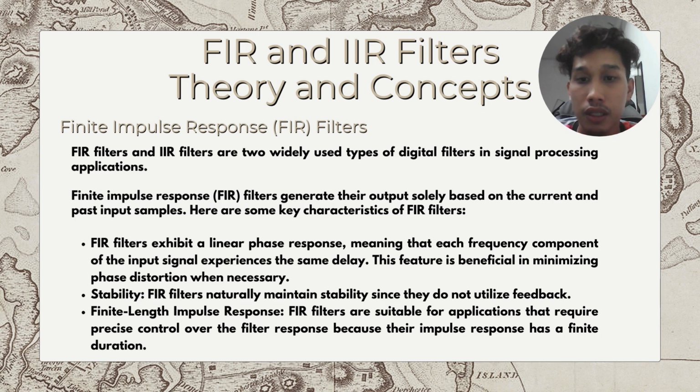Second, for stability, FIR filters naturally maintain stability since they do not utilize feedback. Last, the finite length impulse response. FIR filters are suitable for applications that require precise control over the filter response because their impulse response has a finite duration.